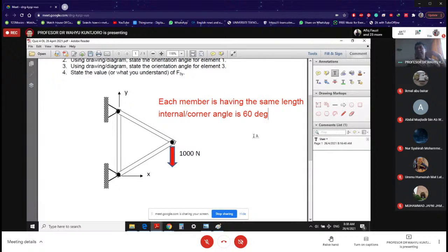The most top is of course your finite element model. If your finite element model is wrong, then whatever you do after that is going to be wrong. So let's say you have done your finite element model and we are working with truss, or a frame, for example, then if your orientation angle is wrong, whatever you do after that is also going to be wrong. I'm going to illustrate that later when we go to a truss example.